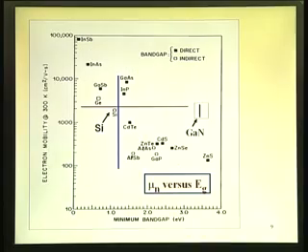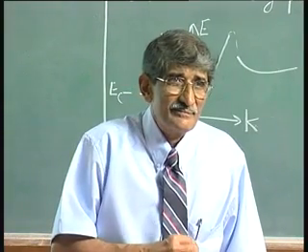So that is why we are not able to choose these materials. In spite of its excellent mobility, we are not able to choose it for microelectronics. For the very reason, these two materials are suitable for microelectronics, because of the better band gap and better mobility. Mobility is at least 5 times larger for gallium arsenide, at least 3 times larger for indium phosphide. We are talking of electron mobility; it is enough if you get the electron mobility. We don't have to worry about the other one. You can talk of devices which depend upon electron transport alone.